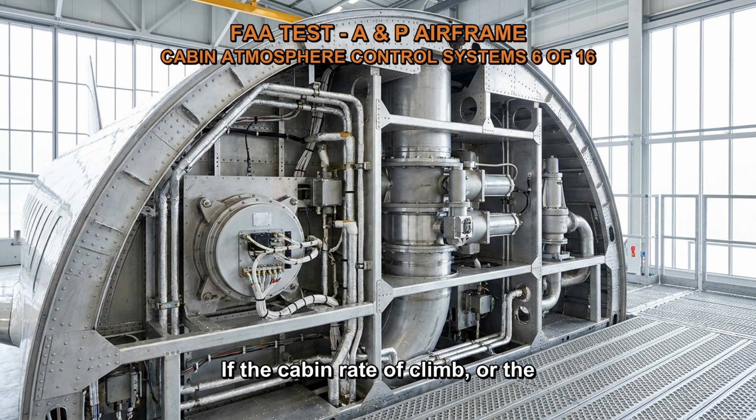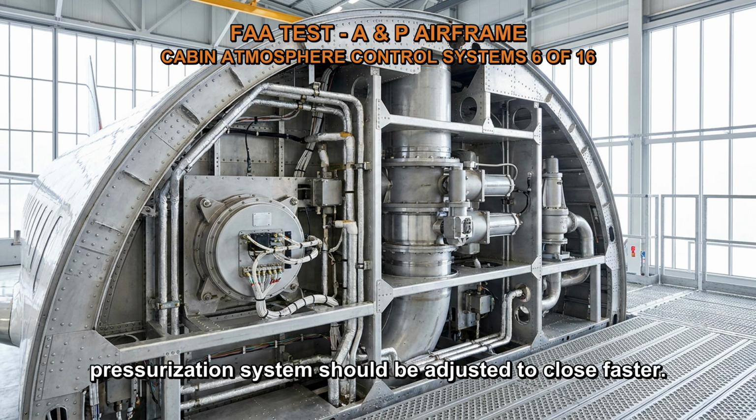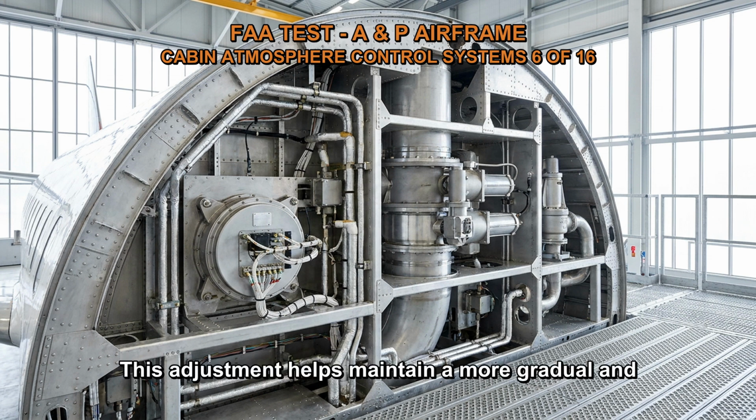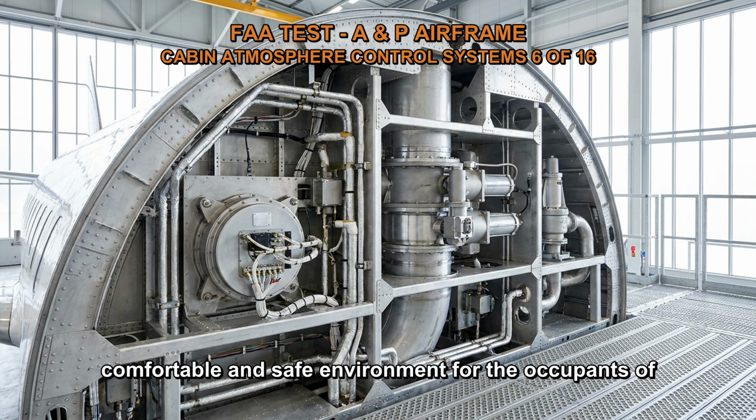If the cabin rate of climb, or the rate at which the cabin altitude is increasing, is too high, the outflow valve in the pressurization system should be adjusted to close faster. By closing the outflow valve at a faster rate, the amount of air escaping from the cabin is reduced, limiting the decrease in cabin pressure and slowing down the increase in cabin altitude. This adjustment helps maintain a more gradual and controlled change in cabin altitude, providing a more comfortable and safe environment for the occupants of the aircraft.